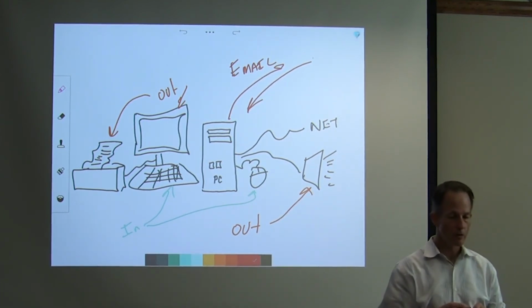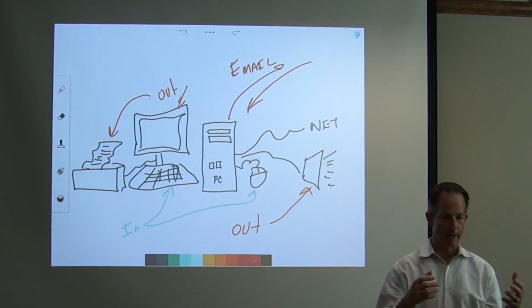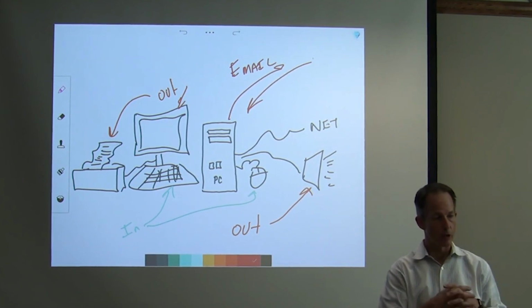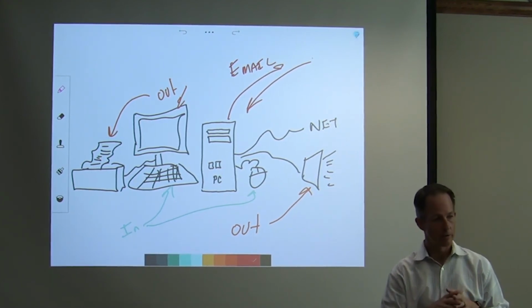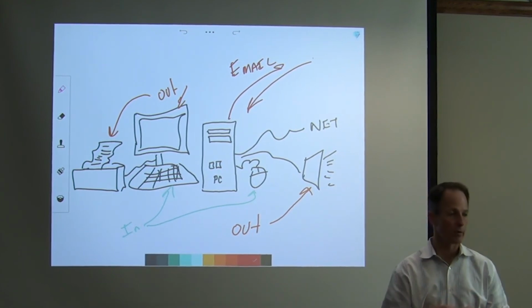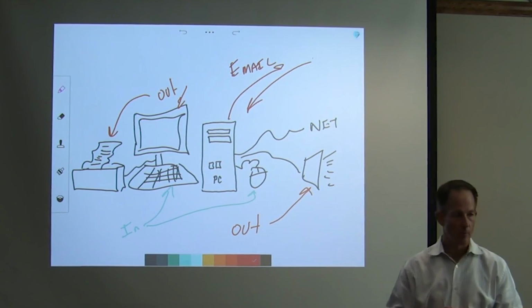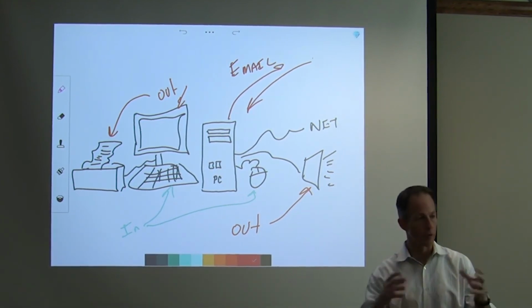Right. And there are a couple other status indicators, like a brownish color. It usually indicates that it's stale, so it hasn't updated for a while. If it's grayed out, then it's disabled. So those are a couple of things to look for on some of the points. Purplish, if you're outlining purple, it's overridden.